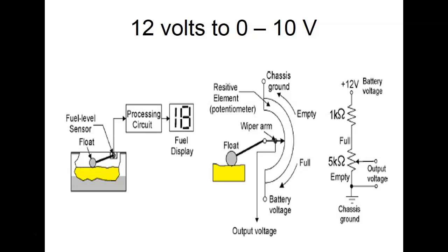So notice the first thing we did was add a pot in there. We added into the top of our pot, we added a what? A resistor. As soon as I see that resistor, there's no way I can have 12 volts with it. So what we would do is, did they teach y'all the voltage divider formula in DC? So we can calculate this.